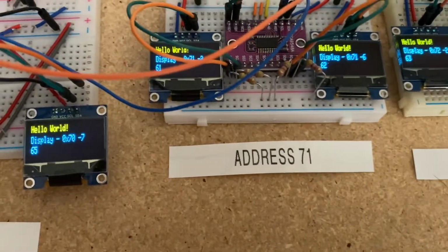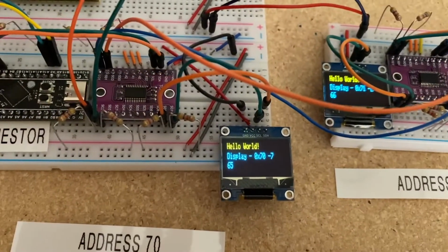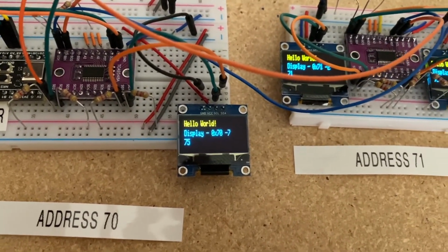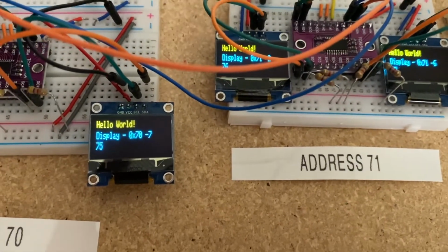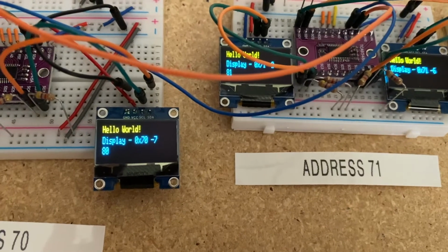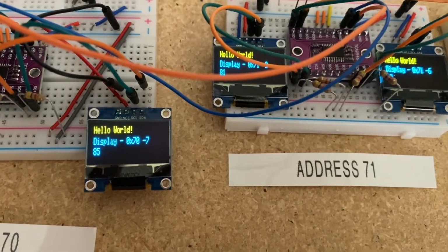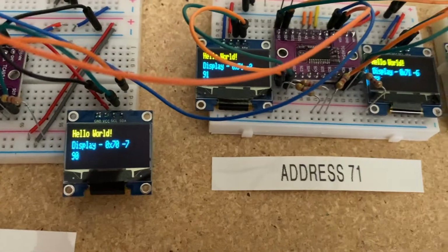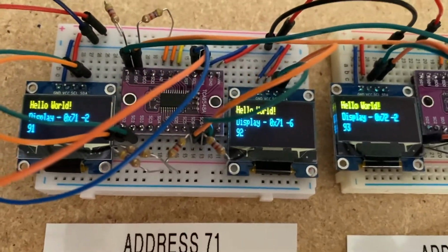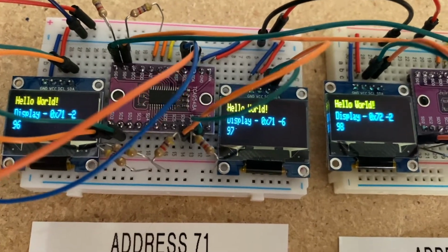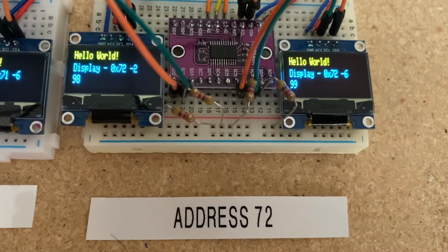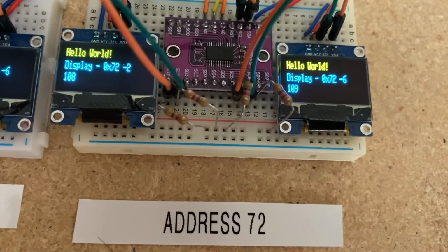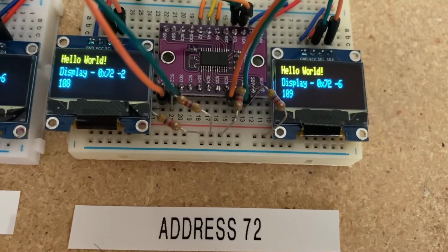Okay, also on the 5 displays, you'll notice that the very first multiplexer has address 70. I'll tell you more about that when I get to the wiring. There are 8 pairs going from 0 to 7, and this particular display is on the 7th pair of the multiplexer that has address 70. And of course over here you have address 71, and the left one is on pair 2, and the right one is on pair 6, and the third one is address 72, and the left display is on the second pair, and the right one is on the 6th pair.